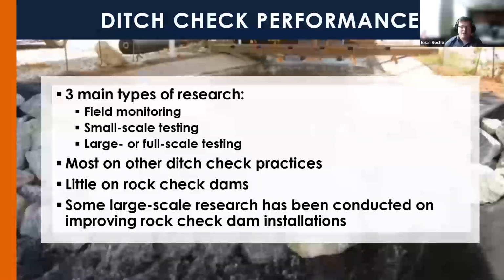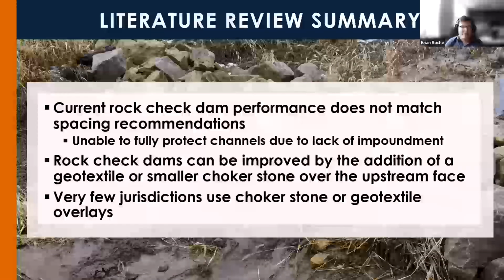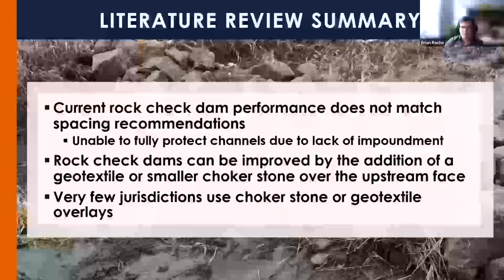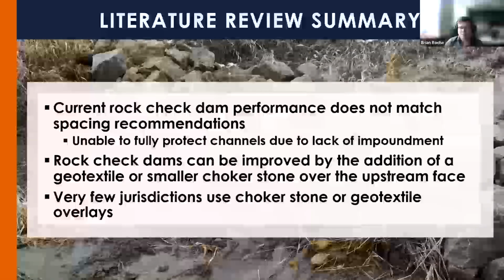We also looked into some past research, which mostly was on other practices such as wattles, through field testing, small-scale testing, and large-scale testing. We found in our literature review that there's a clear disconnect between the rock check dams commonly used and prior performance testing, which indicated that you require a geotextile or smaller choker stone over the upstream face to actually facilitate impoundment, but very few actually use these.